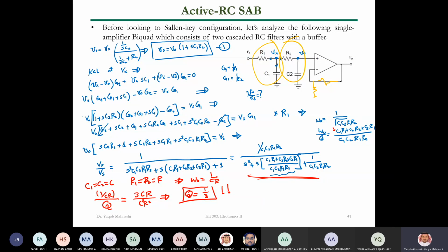What is the problem with this filter? Notice, Shabab, when we give you the filters, we expect you to question the circuit that you have, to criticize it. So what will be the problem here? The quality factor is low. Exactly, low quality factor, and we proved that through our analysis last time, and that's why we said we can improve the quality factor by going to the Sallen-Key.